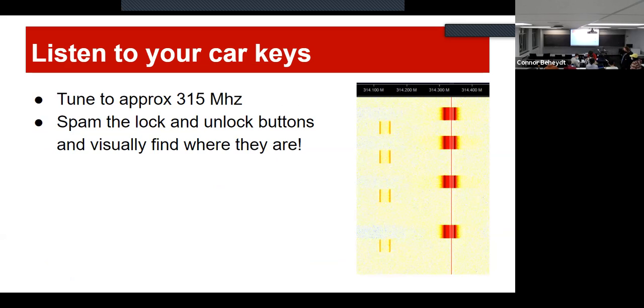It samples all the frequencies going back and forth. If the signals are quite quiet, especially commercial FM signals, click the settings button and turn up your gain. That helps a lot.